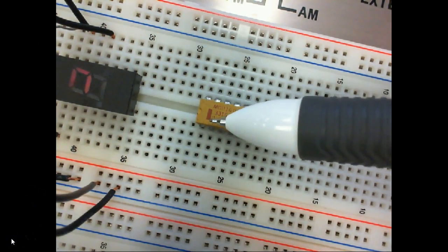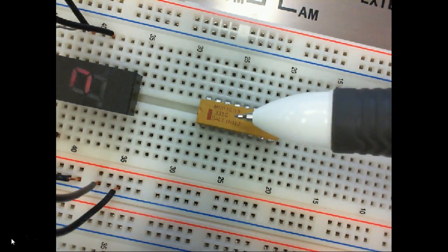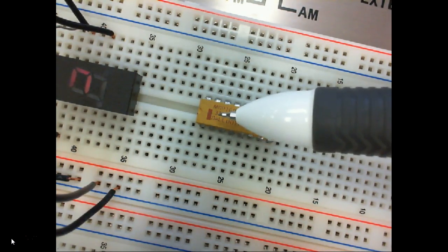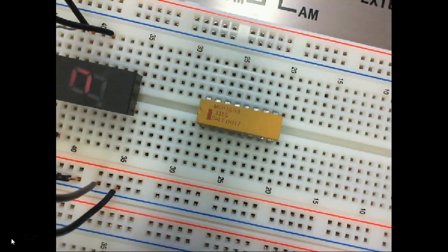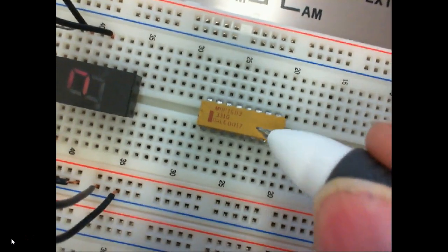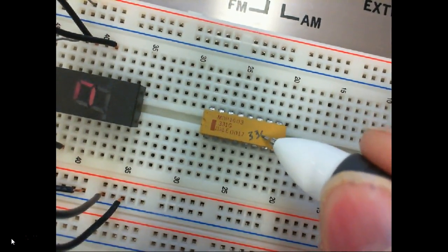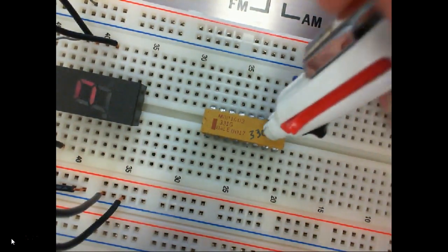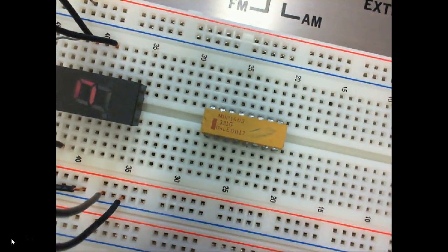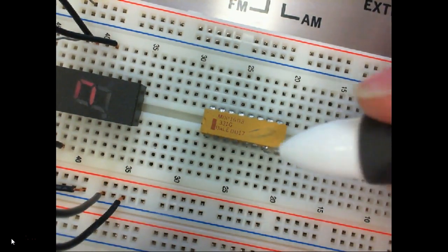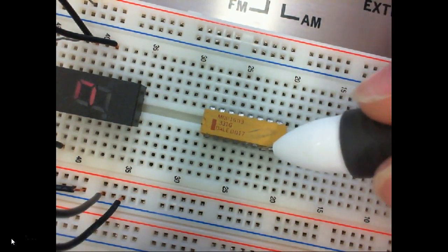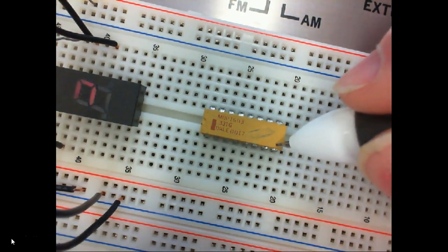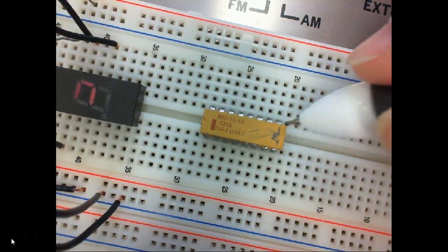So it's kind of like a color code, but instead of colors it's using digits. These are through-hole parts, and it works basically like the color code. 3, 3 is your first number, and the last number tells you the number of zeros to add. So 3, 3, and 1, 0. That means this is a 330 ohm resistor. The resistors are in there crossways. It's a 16 pin DIP, so that means we have 8 resistors in there, and the resistors are across it like that.